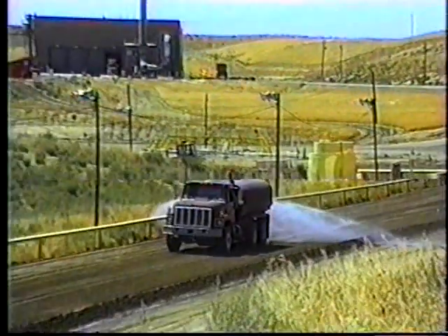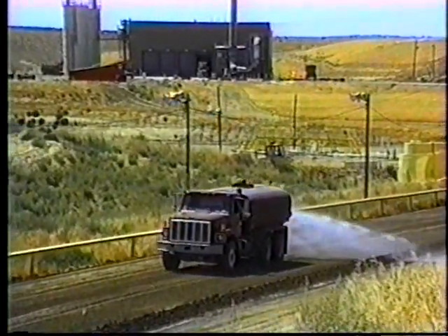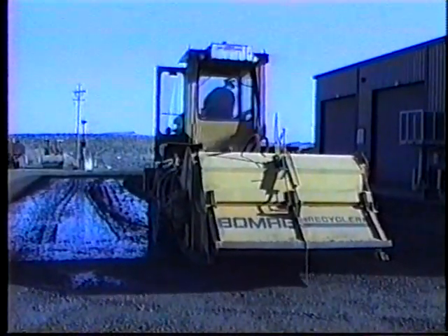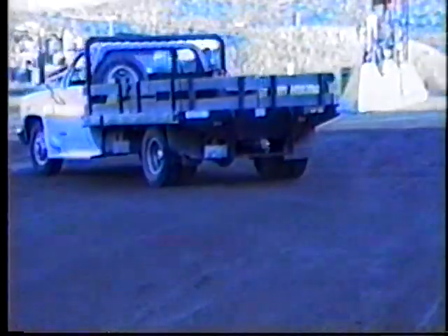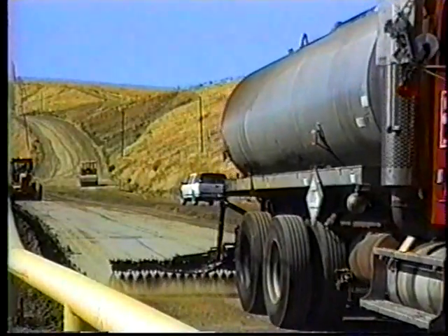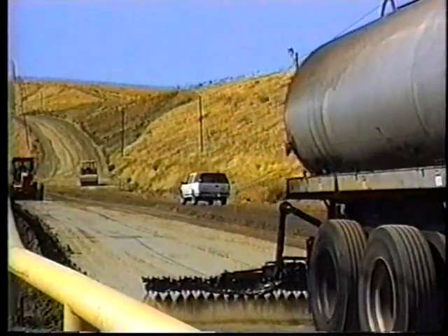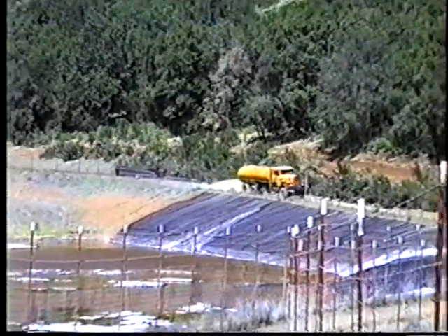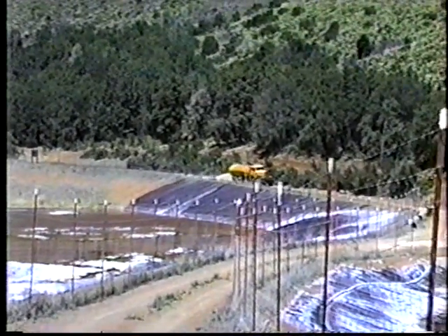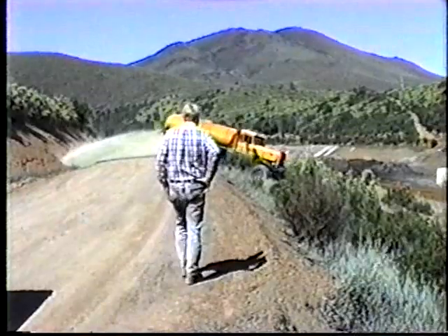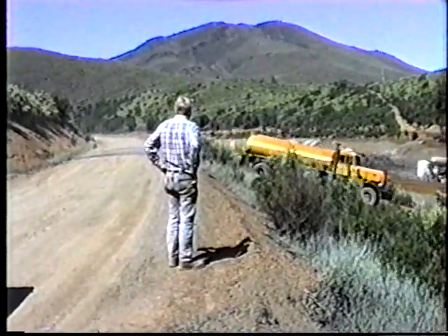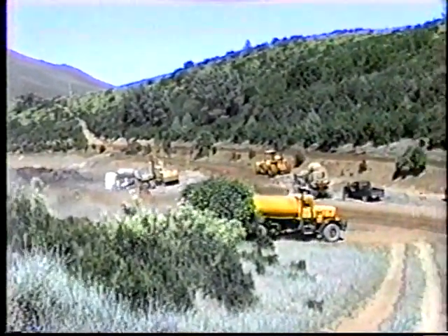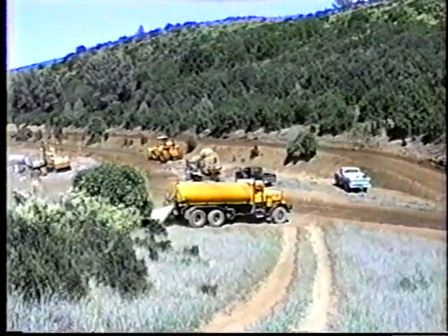At this hazardous waste landfill, road oil is used as a surface penetration treatment for dust control on secondary roads and mixed in for full depth treatment on heavily used main access roads and equipment service areas near the shop. This dual-use type of application is typical and exemplifies the versatility of the resin-modified emulsion technology. Another landfill uses surface penetration application on all of its roads, except for one very sharp curve where road oil is mixed full depth with the aggregate and then compacted to create the shear resistance and tensile strength needed to withstand the tight radius turning action of fully loaded trucks.